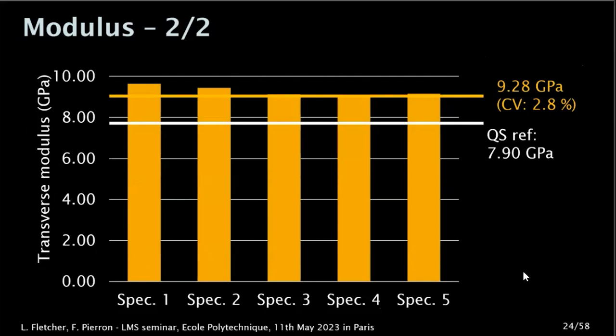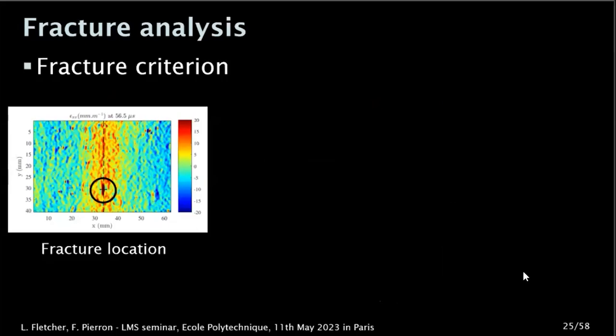We've tested thermoplastics, and in that case you have much larger effects, sometimes ×2 between quasi-static and high rate. But this is a thermoset, it's not super sensitive to strain rate. What is interesting now is the fracture analysis. So can we get a fracture stress from that? It's a little bit more complicated now, because for that we need to space resolve the stress. And we can't really do that, but there's a way around it.